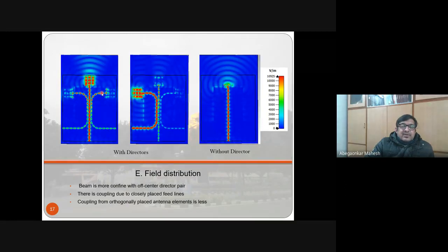These antennas are also getting excited to some extent. So there is coupling happening to some extent, and that coupling can be reduced by what are known as electromagnetic band gap structures. Right? Those are also used a lot in our lab. We use electromagnetic band gap structures to reduce this coupling, because if you want the center antenna to be excited, only that should be excited. The other two should not be excited.